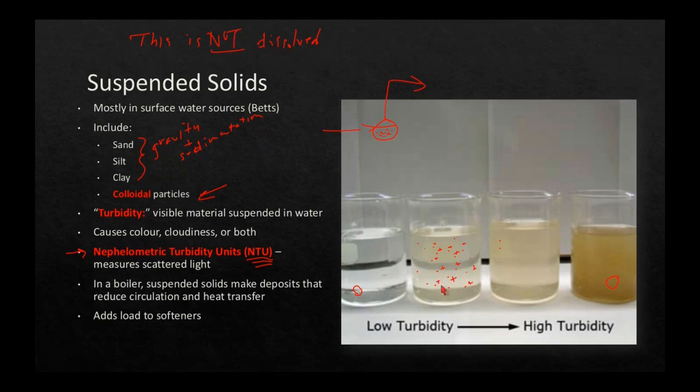They're just charged particles, and they're so small, and because they have these charges, they stay very evenly dispersed throughout the water, and gravity cannot make them come together at the bottom, right? I mean, we would want them all to sink to the bottom and leave us sediment, then we can deal with it, we can discharge it. But those little charges, how do you bring them close together when they all have the same charge? So gravity cannot work.